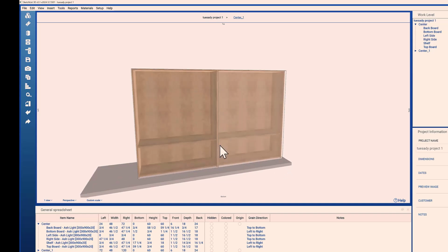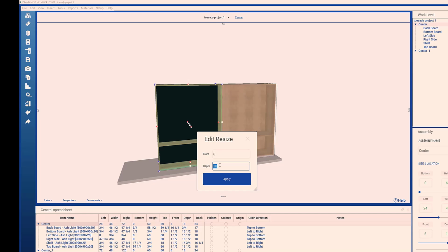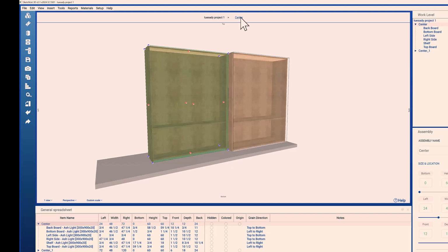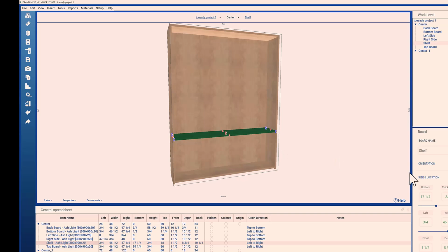Okay. And again, the right dots resize. I could make this into any size. I say here, the depth is 18. I want 12. I can do that. I can go into a shelf. I can go into an assembly and take this shelf and say, I want to make multiple copies of this. And I'm going kind of quickly because I just want to establish a flow, and we'll go back into the tools in more detail.